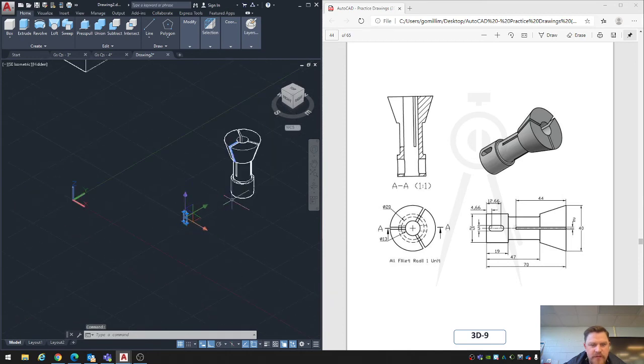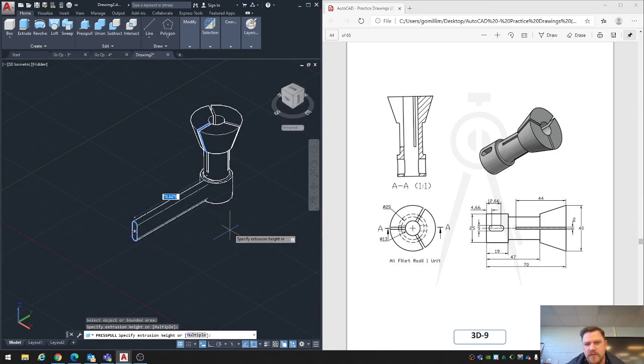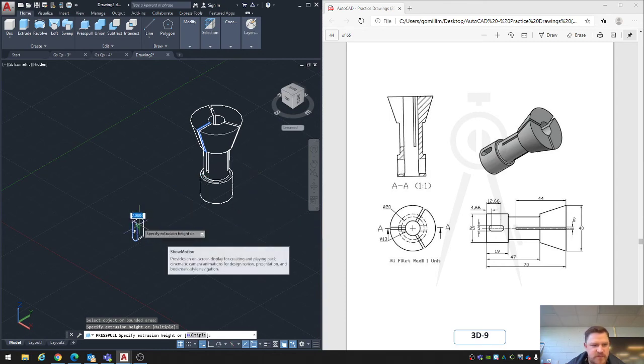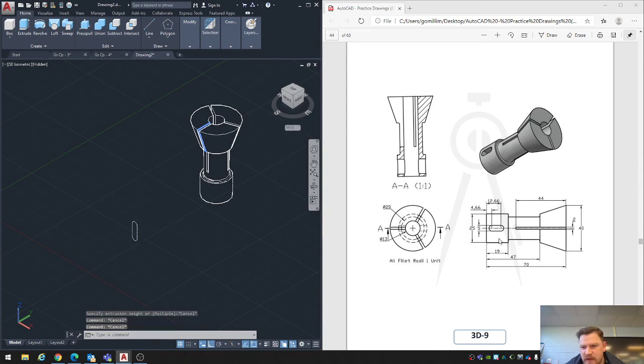But anyway, what you would do at this point would be to press pull this basically into this and then use the subtract tool again. It looks like it actually goes all the way through based on this section view. So get the size of this thing right. Let me just do this math here. I guess it would be 12.66 plus 5, 13, 14, 15, 16, 17.66.